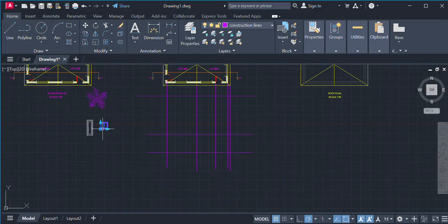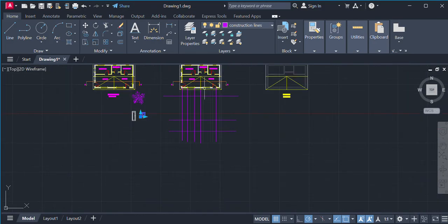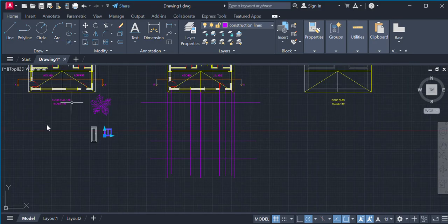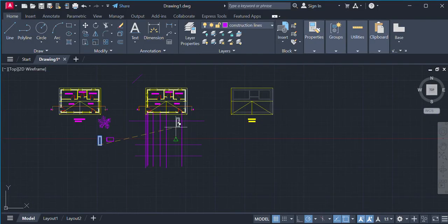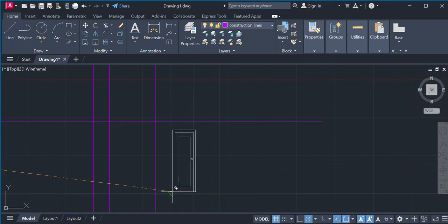Okay, then let's go to our window. Automatically it opens its properties because we were on properties, and the windows we have here are the big ones. I think it's 1500 windows, so we can extend it over here. Then the window height is 900. That's fine. So what you're gonna do, you can take your door, copy it, and snap it right by the corner and match it with where your door is sitting. So your door somewhere here.